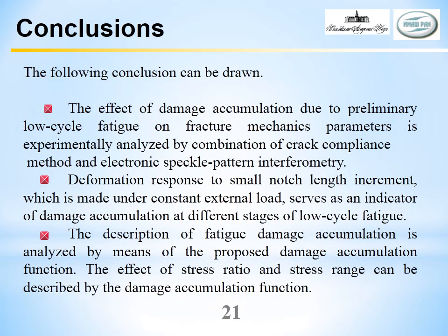And conclusions of my presentation. The following conclusions can be drawn. The effect of damage accumulation due to preliminary low cycle fatigue on fracture mechanics parameters is experimentally analyzed by combination of crack compliance method and electronic speckle pattern interferometry. Deformation response to small notch length increment, which is made under constant external load, serves as an indicator of damage accumulation at different stages of low cycle fatigue.